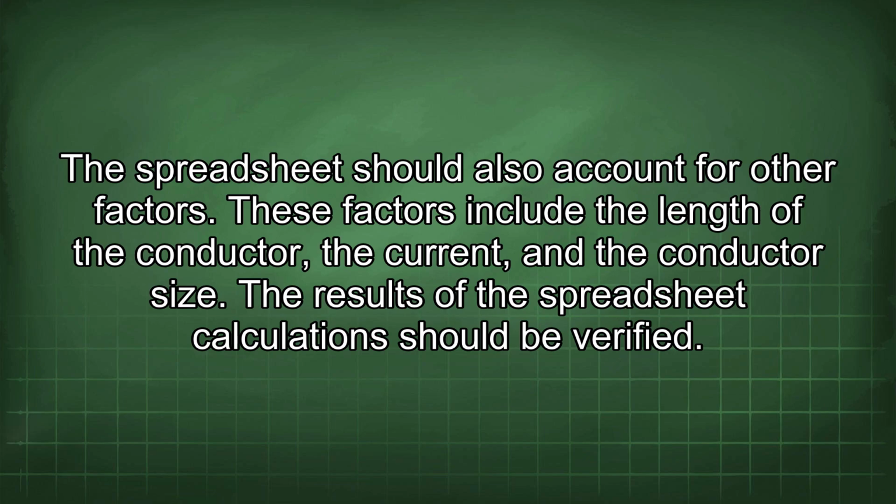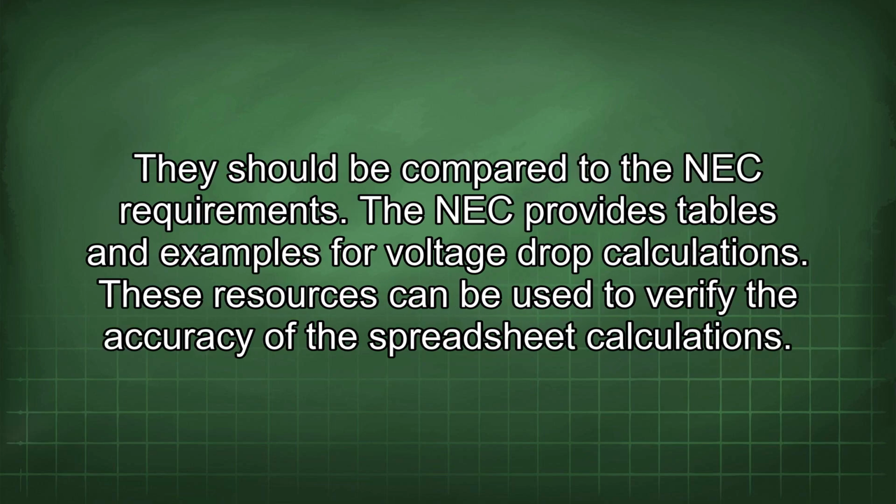The results of the spreadsheet calculations should be verified. They should be compared to the NEC requirements. The NEC provides tables and examples for voltage drop calculations. These resources can be used to verify the accuracy of the spreadsheet calculations.